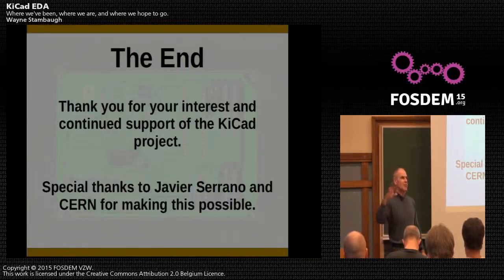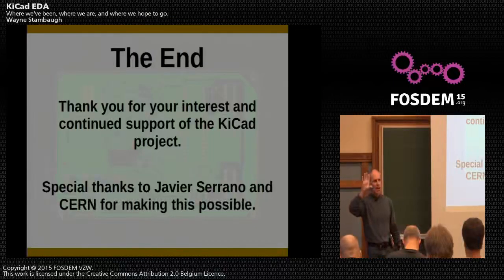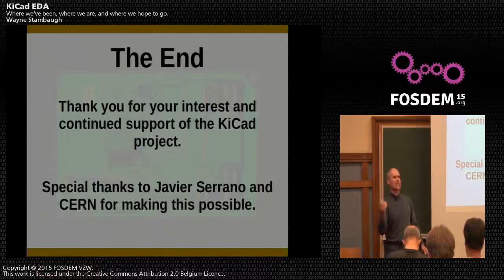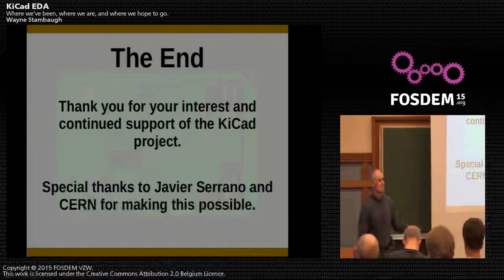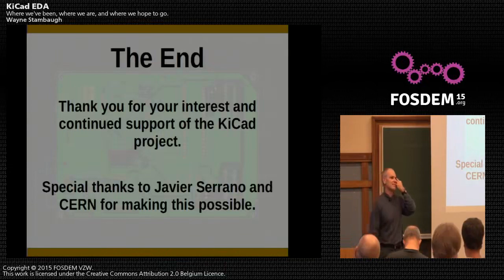And libraries as well. We have this library management tool called the footprint library table. You can point it to an XML file and tell it, hey, this is an Eagle file, and it'll pull all the footprints out, and you can look at them just like any of our footprints, and then you can save them as KiCad footprints. But the schematic and the symbol libraries aren't done yet. That's after the next stable release.